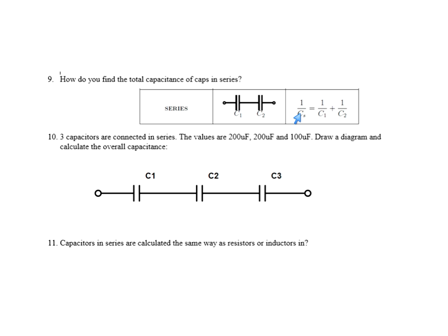It's 1 over x. Now look at this problem right here, typical problem. 200, 200, and 100 microfarad. There's the diagram. Label these. Well, I can take the reciprocal of 200, the reciprocal of 200, the reciprocal of 100, hit the equal sign, take the reciprocal, and I would get the answer. If I did that, I would find it would be 50.